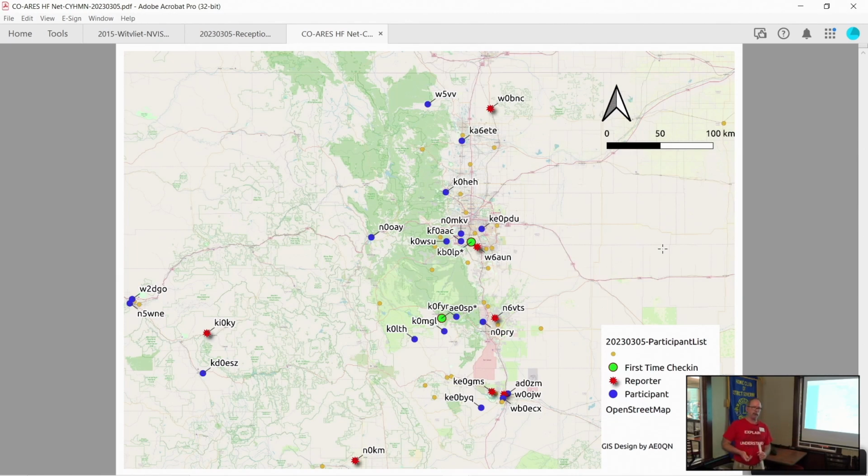So my focus has been on end-fed antennas, and there's end-fed half-wave antennas that Jim used to make and sell before he went to random wires. Those work on multiples, so they'll work 80-40, they won't work 60 without going out and removing a clip in the wire. End-fed random wires of the proper length will work all the bands within a range, so 80, 60, 40, 20, 10, 6 meters. So my focus has been on an end-fed random wire antenna.